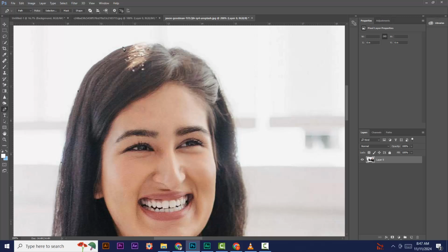To create curves with the pen tool, click and drag when creating an anchor point. This will add handles to the point, which allows you to control the curve. The direction and the length of the handle control the direction and sharpness of the curve.